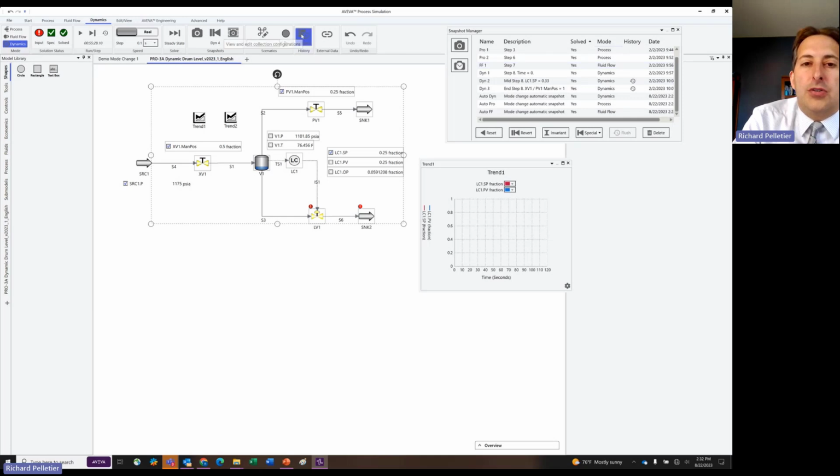The other thing that you can do is there's an area here called the History Manager, and this defines what points of data are stored within my dynamic run history. And so it works between this multiplier, which goes against the step size, as well as the number of points that I have defined here to give different ranges for different sets of collection information.